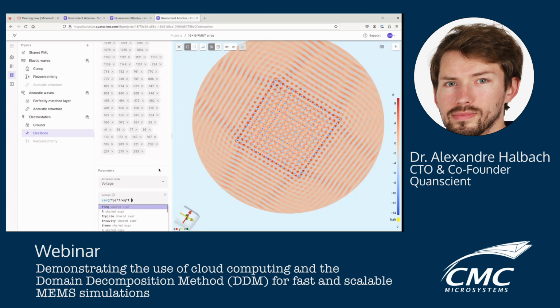You might be able to just use an expression that measures at every point in the array what phase shift you need to apply to focus at the given point. And this phase shift would be an expression, not a constant like here, but something that depends on the radius, the X, Y, Z coordinates. So that could be done pretty easily as well.